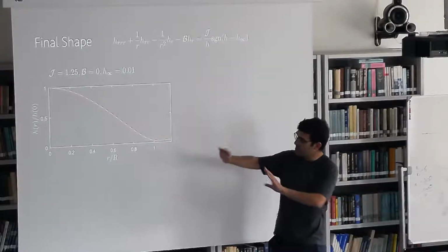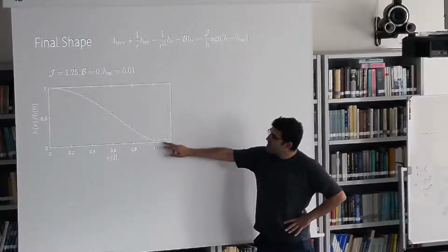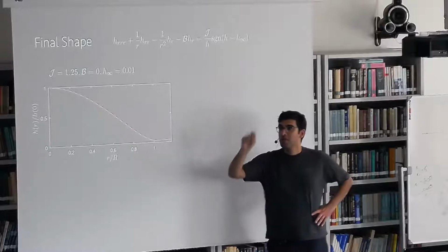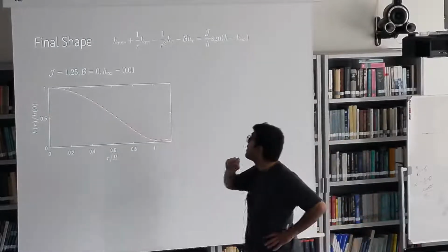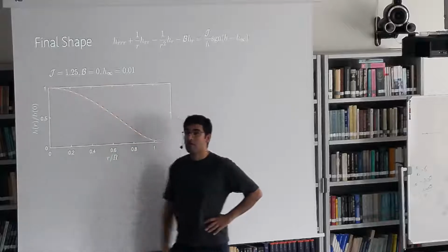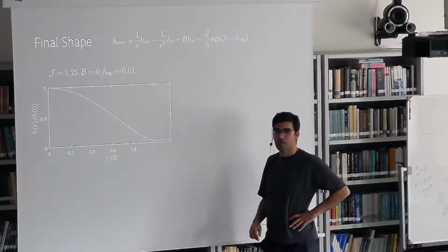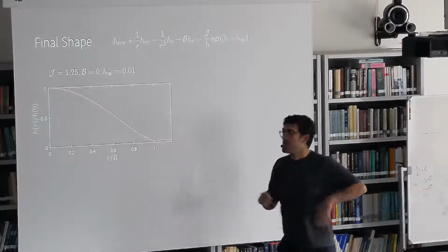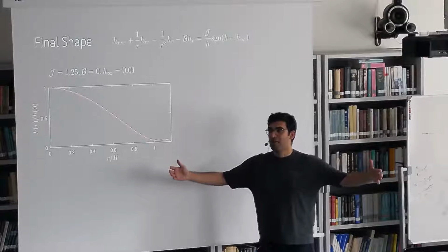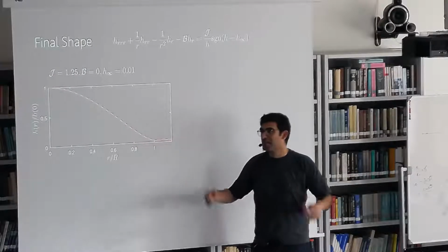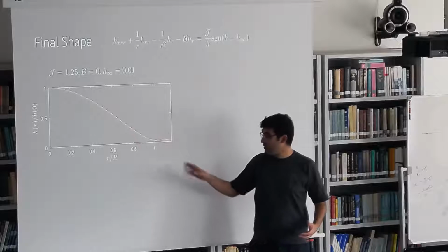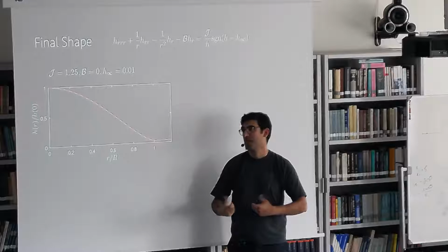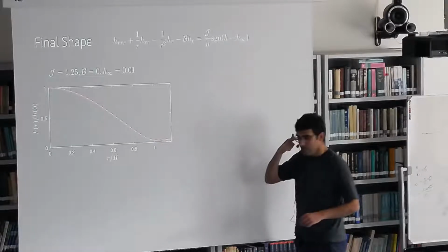So this is not dynamic, this is t infinity. One of these lines, I forgot which one, is coming from the finite difference solution, one of them from this solution. No, there's no gravity, so B is 0. Yeah, you can add the gravity rather easily, and I will show some results with gravity. Yes, exactly. If you have gravity, you get this pancake form. But you get this final shape exactly because, another thing I can say, this curvature is rather high, but yield stress can sustain curvature. So that's the main difference.